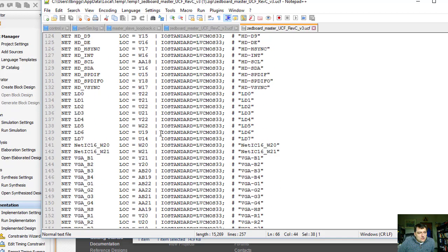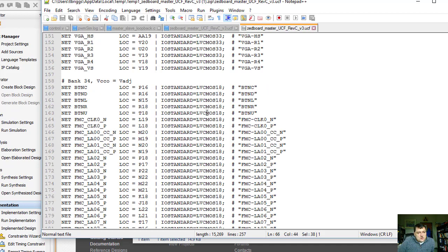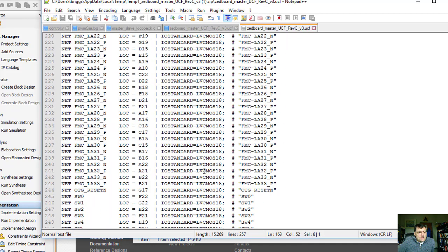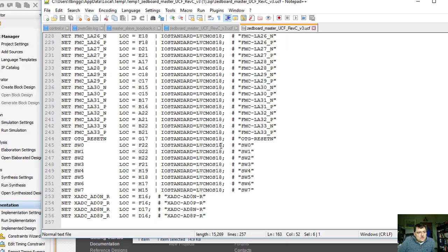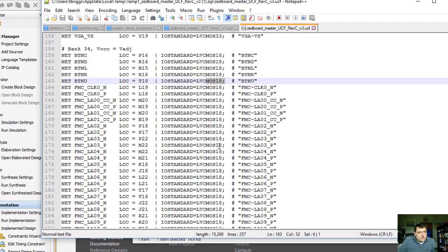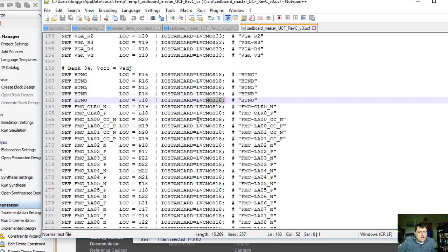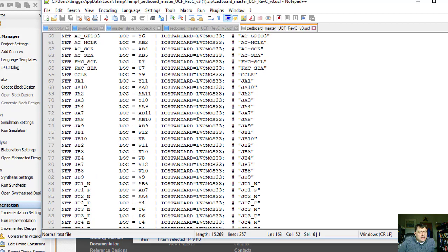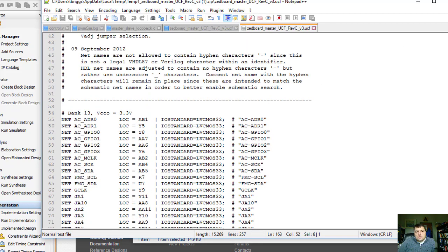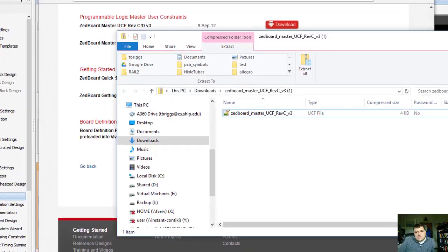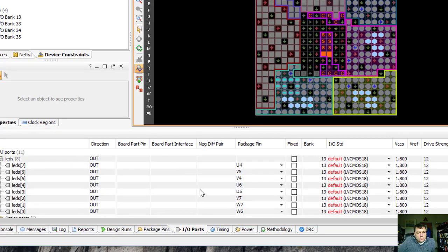If we looked at our various push buttons, the push buttons are 1.8 volt, and we've got to find those LEDs. Oh, here's our switch. The switches are 1.8, and one more time here, looking for these LEDs. Here they are. LED 0 is the 3.3 volt. So it looks like everything is living on the 1.8 volt except for the LEDs. And I guess you'd kind of expect that, just because LEDs need just a little bit more voltage to manage the current. So if that's the case, we can come now and roll through this configuration, and my LED 0